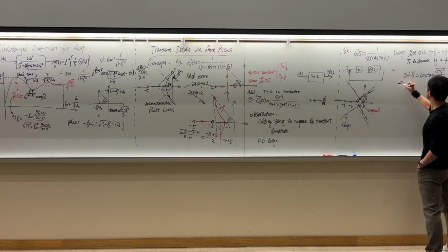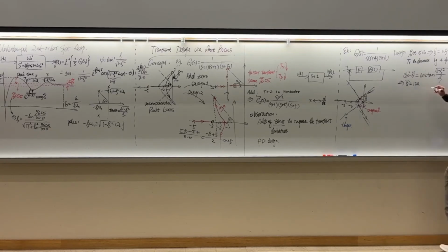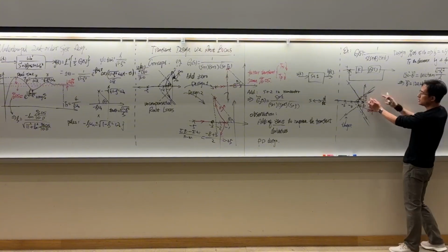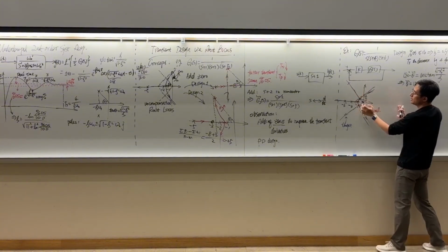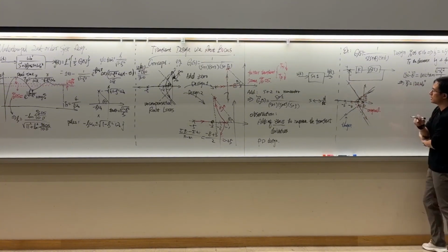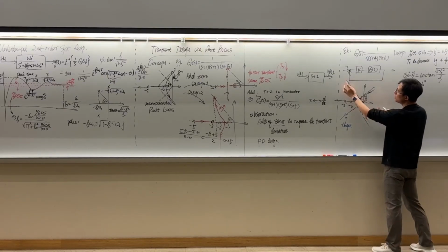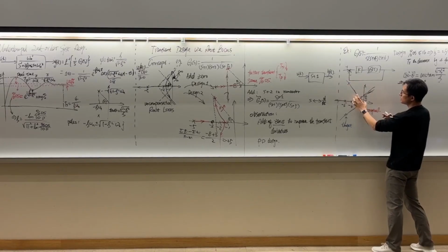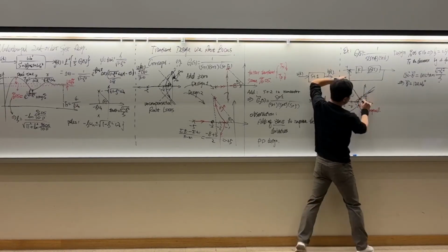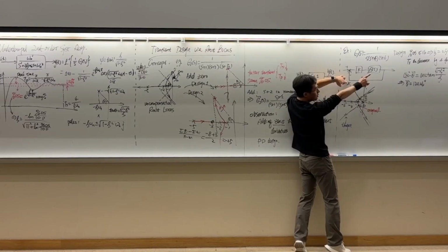So from here, you can get theta tilde 120 degrees, or 120.26 degrees. So you know this target line now, and we can start the design. To have the closed-loop poles be here, with this angle, we will be satisfying the percentage overshoot requirement.